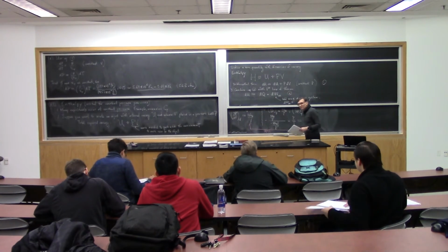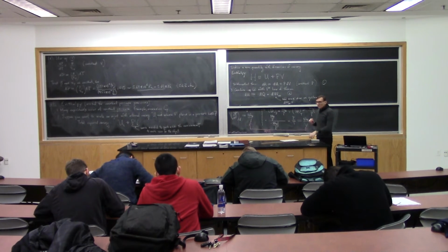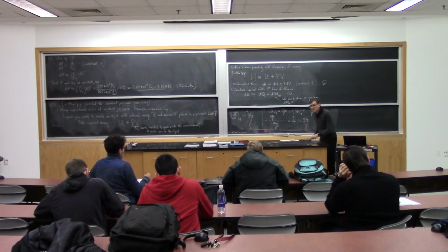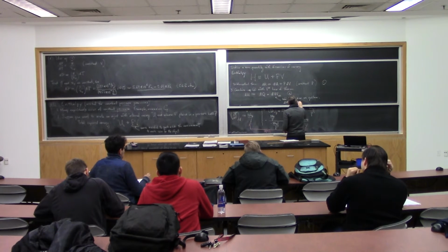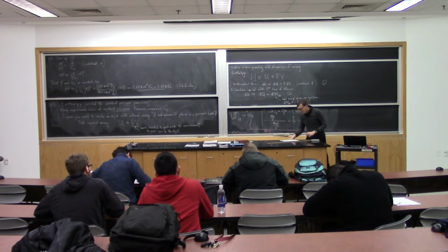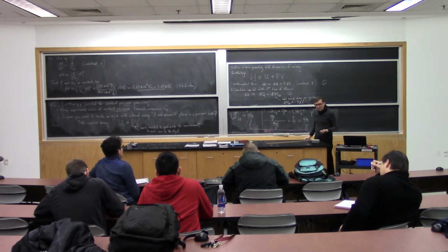All the work is going to be classified into 1 of 2 groups. It's either expansion compression work from a volume change of the system. We know how to write that in infinitesimal form. It'd be negative P dV. That's how you represent expansion compression work from a volume change.